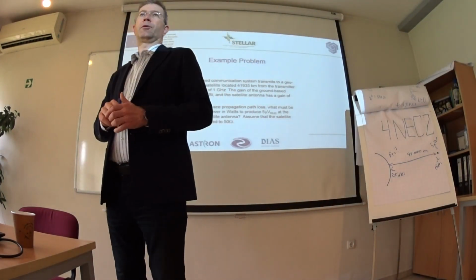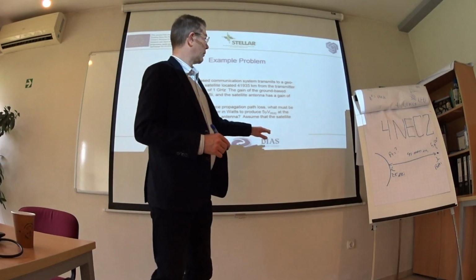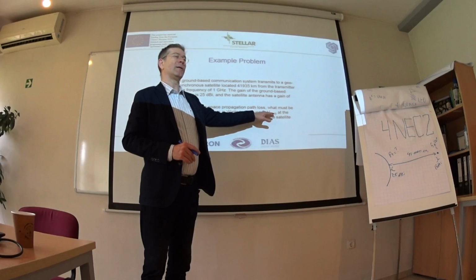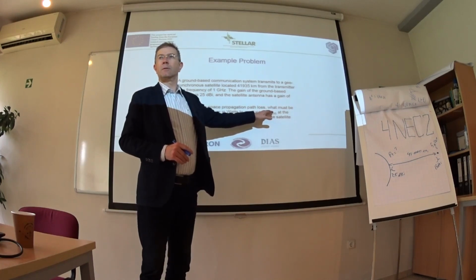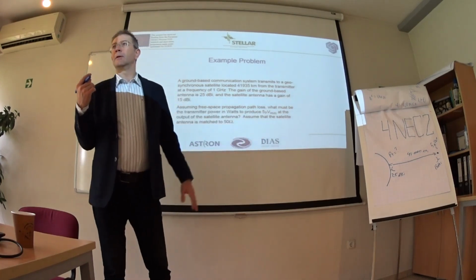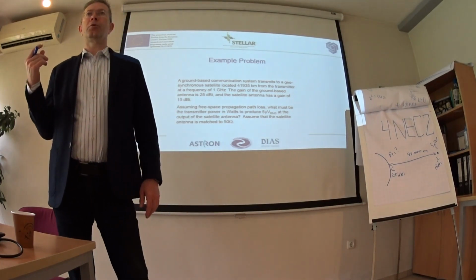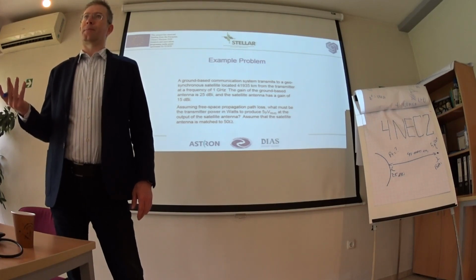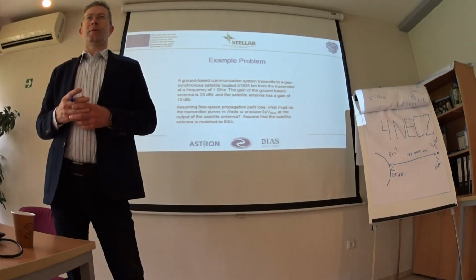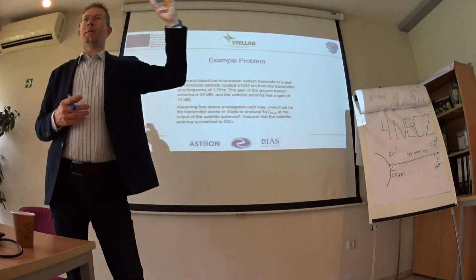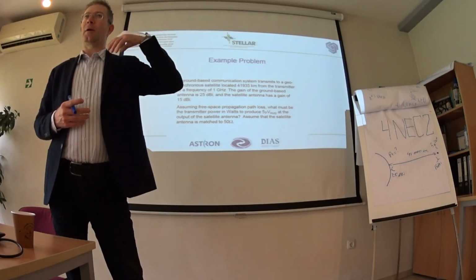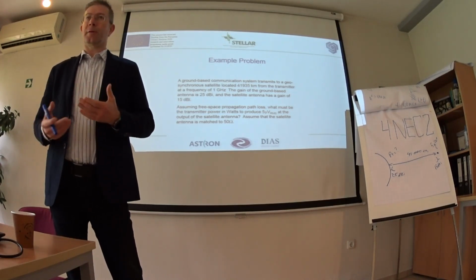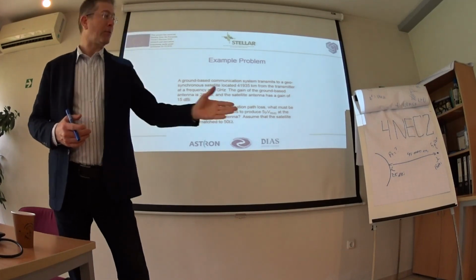Why is the problem positioned like that? Because we know the sensitivity of the receiver. So we think that 5 microvolts on its input will produce enough signal to noise ratio so the signal will be detectable. In other words, we are putting a receiver on a satellite. We know where the satellite is and we would like to know how much power we need to transmit in order to close the link. Can you solve it for yourself?